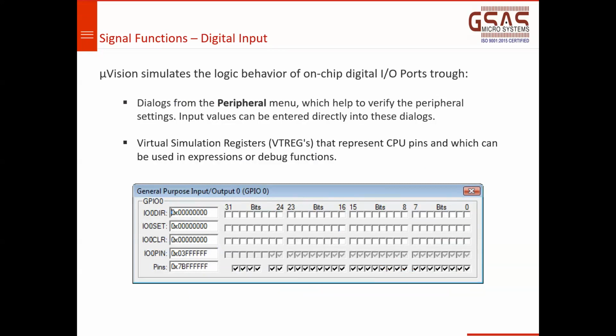For example, they may multiplex the GPIO with UART transmit or receive, or with an external interrupt, or with I2C or SPI. This way the pin count is kept low, and the microcontroller becomes more powerful because it has all the peripherals required for your application. That is where technology is going.